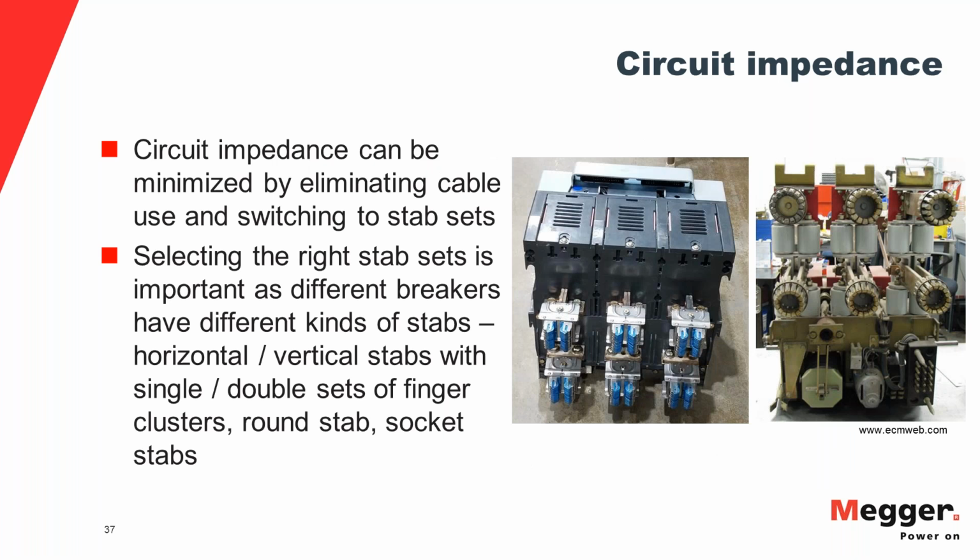One good way of eliminating or minimizing circuit impedance is by eliminating cable use altogether and going for stab sets. The challenge here is having the right stab sets on your test sets that are compatible with the stabs of the breakers, because breakers come in various shapes and sizes.